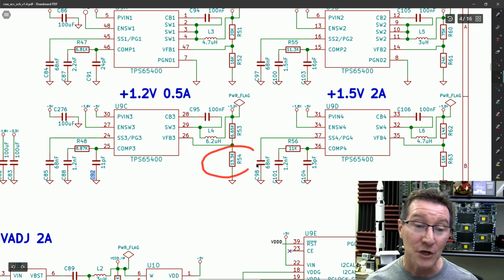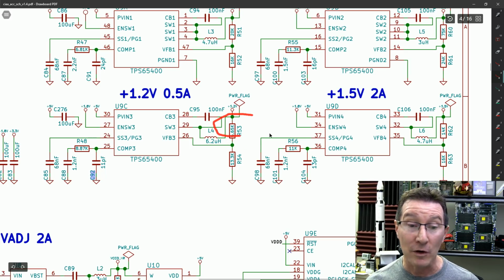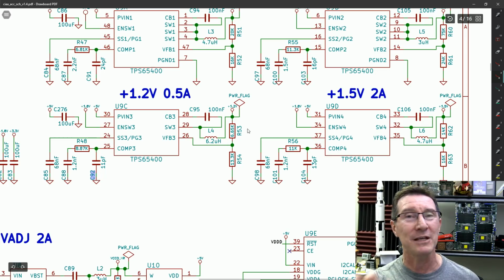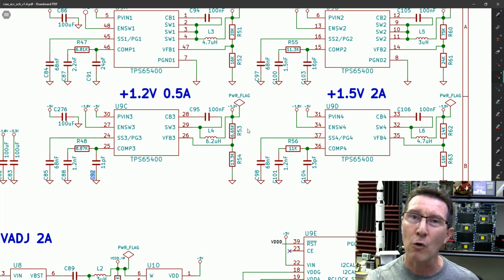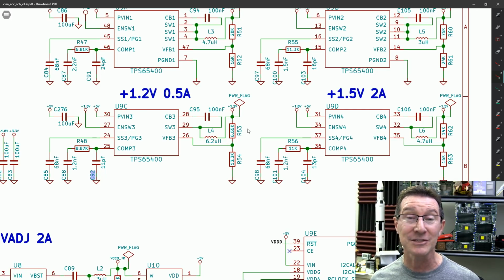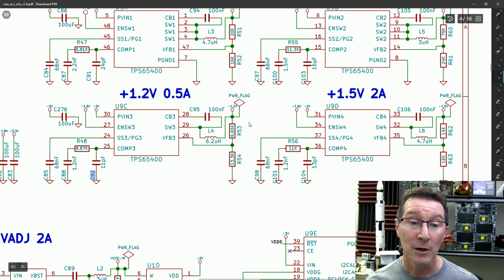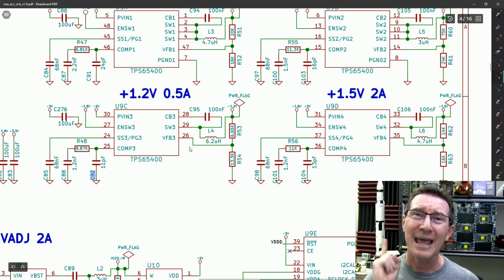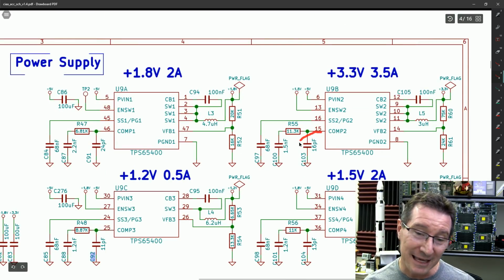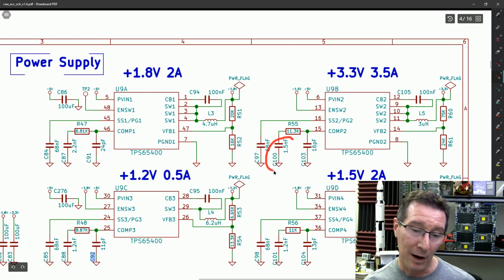You've reused one of your parts here, and sure, you've put in an extra resistor, and sure, it's more board space, and sure, that might be important if you've got a real ultra dense design. You may not have the luxury of being able to put two resistors in parallel, but in probably the majority of cases in practice, you are going to have the room to put in the two 10K, or make room. A good PCB layout designer can always make room for that extra resistor, just so that you reduce that one extra BOM item. And you can do this again, 16 pF up here, 1.2, 1.5 nanofarads.